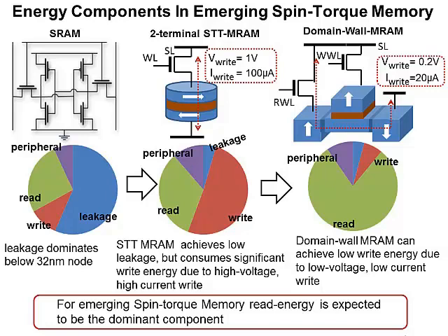One of the disadvantages of conventional STT-MRAM is write energy. In order to write in the free layer of this cell, we need to inject a good amount of charge current across a large voltage, and that constitutes a good amount of write energy per bit cell. But in the last 5 years, the solution to this problem has been explored widely, and several low energy write schemes have been proposed and demonstrated experimentally.